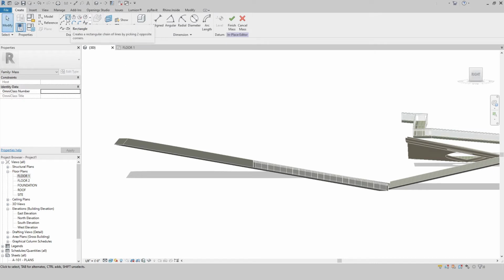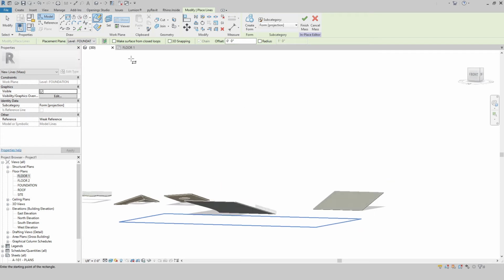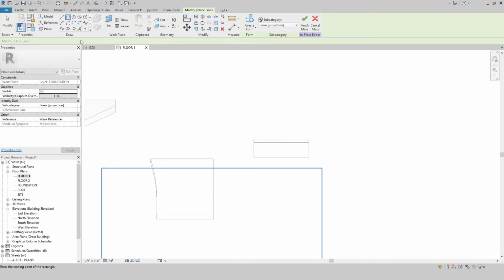And you could just go and draw out on one reference plane, one square, another reference plane, another square at a different height, just loft those two together. A lot of times, though, it's a little bit easier to draw some reference planes as targets in the floor plan first, which I didn't do yet, so I'm going to do that right now.